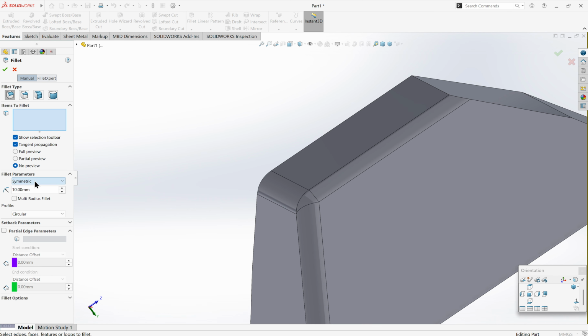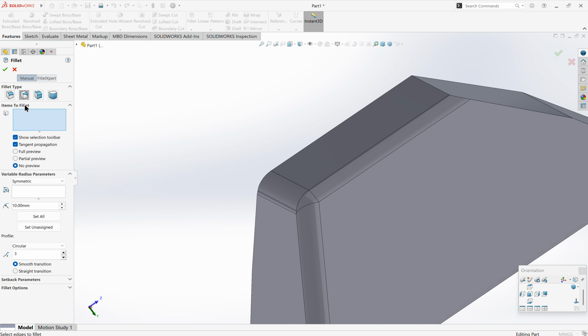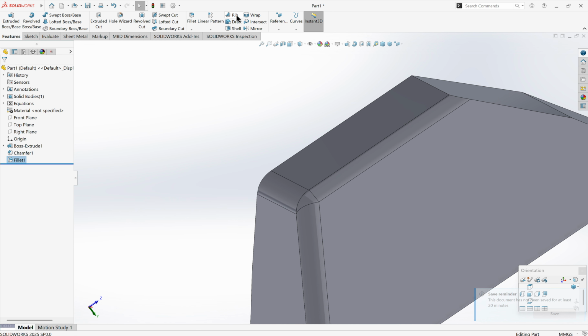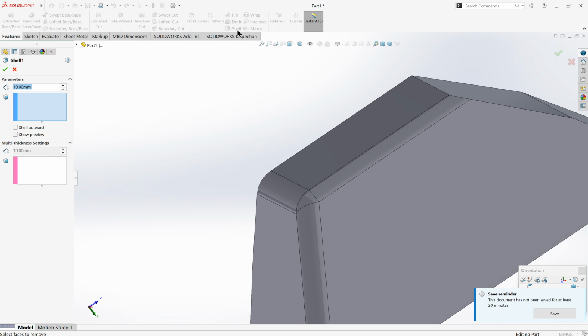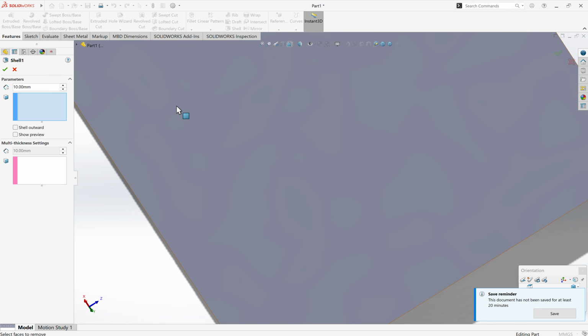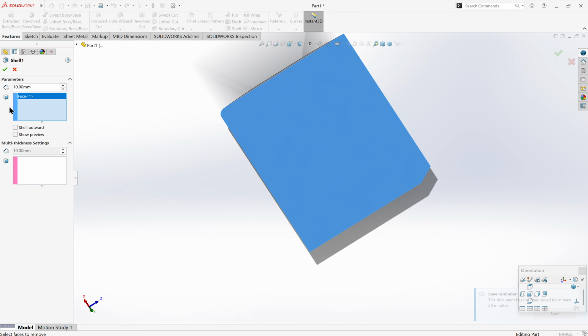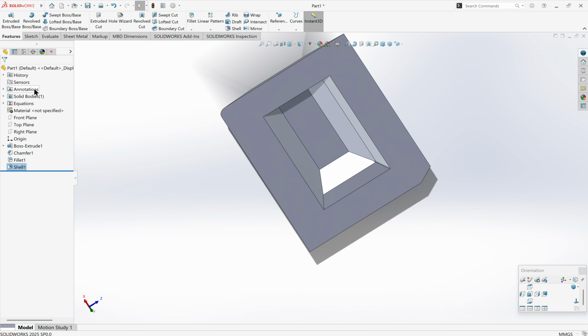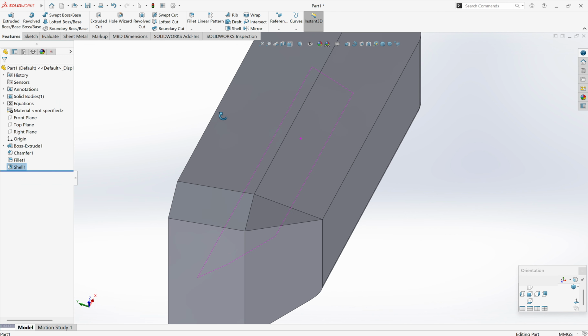If you look around them, it's settings, increase that, decrease that. I have never used these. This is at an angle. Okay, you change them. Now the red, these we don't need. Shell is a thing where you press on this face and set the thickness of the wall, let's say make it 30. Then press okay, 30 and enter. Look, you made a hole inside.